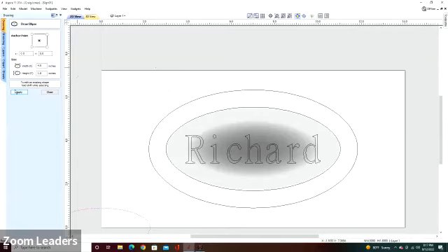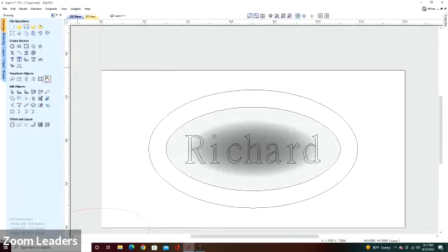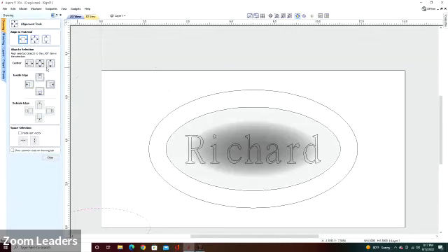So you can do things like that. I often use the center of the workpiece as the 0, 0 because that way I can center it. But there is a tool in your CAD package called alignment. And you can say align whatever you have highlighted to the center of the board. Boom. So that puts it right there in the middle. So you can do your ellipses. And in a minute, we'll come back around to what we do with those things.